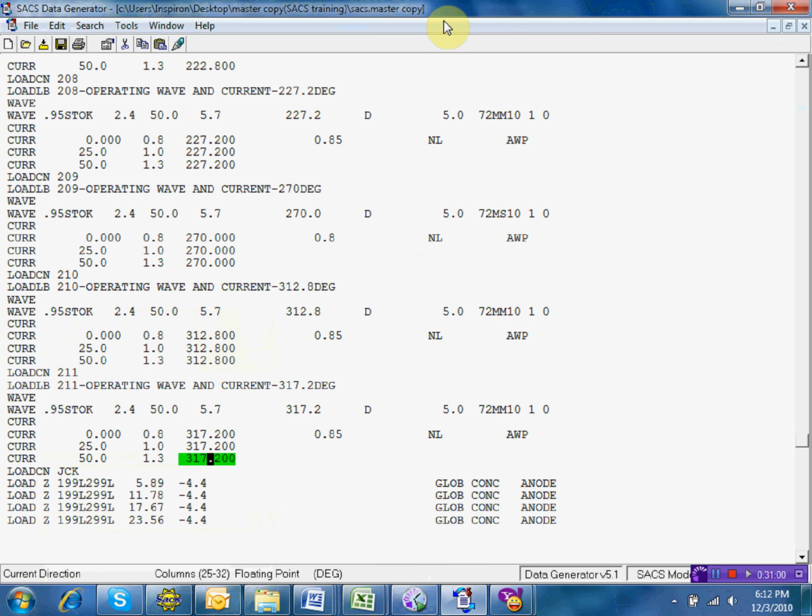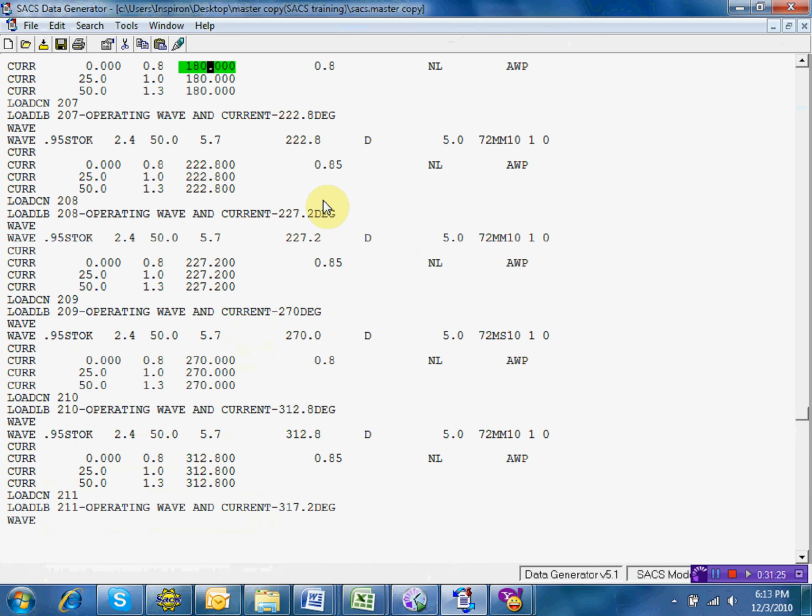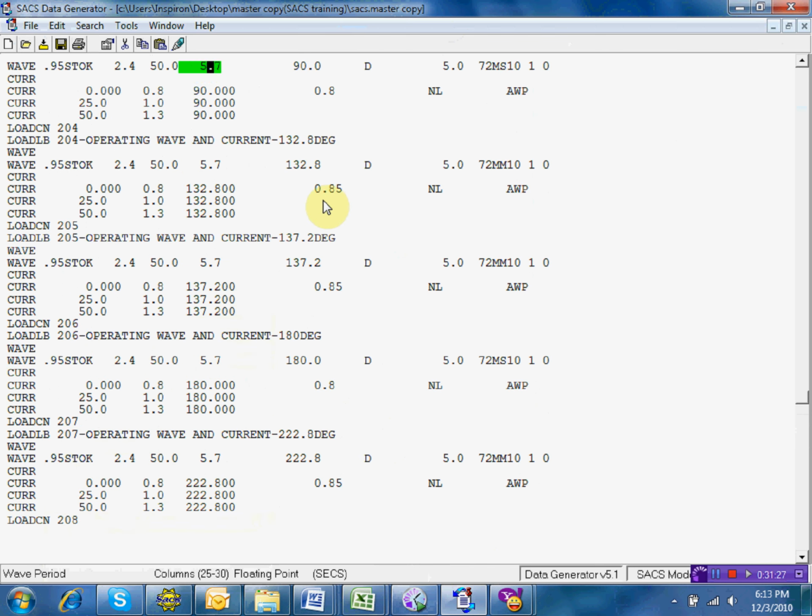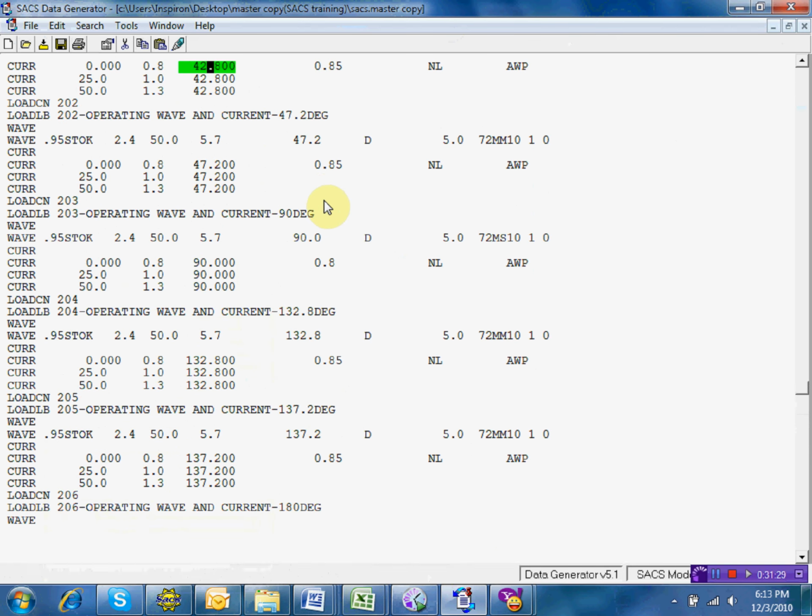How about if there is a tender rig at the platform? Because this is quite complicated when there is a tender rig. Like for example, this is the well. You have a certain well pattern. You will put the center of the one well, one load condition, and you have 12 attack directions. Another location of the well, so your top side or the rig will be put on that direction, attack direction in this direction.